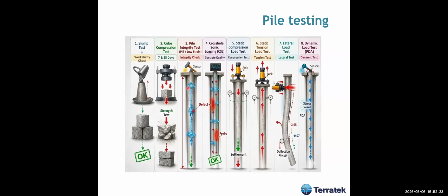We do a lot. And we always specify in concrete piles mainly to do it in all piles to check for defects. The board piles, which I have shown you, we always do cross-hole sonic tests. This test is to check also for defects in the concrete. We have these access pipes pre-installed in the cage. We have done a lot of those tests.